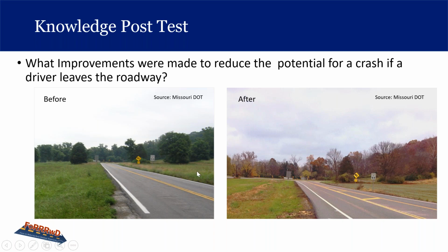Very good. So yeah, at this location, paved shoulders were added, and there appears to be a bit of an edge drop off that could be mitigated by the safety edge. Maybe they did not use safety edge like they could have here. There's also a centerline buffer area. The clear zone looks good both before and after, and a tree appears to have been removed from the inside of the curve too. So they removed this tree from the clear zone, and look at how it really opened up the sight distance once it was out of there.